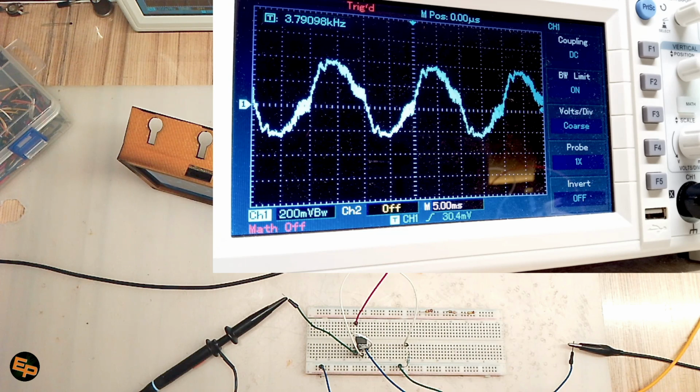That was the one basically picking all sorts of interference from the outside world, from the environment, and shoving it into my op-amp, so that my op-amp would pass it on the output. And if the op-amp had been configured as an actual amplifier instead of a buffer, I would have seen a much bigger signal on the output. Okay, which is a bit of an ouch.